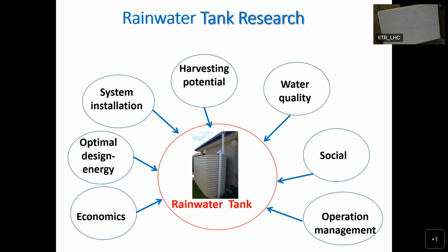So they are not designed to capture all the rainfall at heavy intensity. That means there will be some portion of rainfall, during some period when the rainfall is more than 120, that will overflow from the gutter. That's one factor. The second factor is wind.